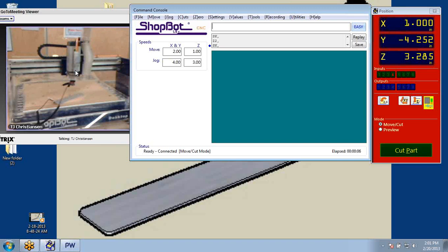All right, got a good question here. Tell us about why you should square the tabletop or spoil board. Well, one thing is humidity is going to come in there and change the thickness of it. It can alter. I know I've seen mine down here in North Carolina, with the drastic temperature changes, hump up in the middle.